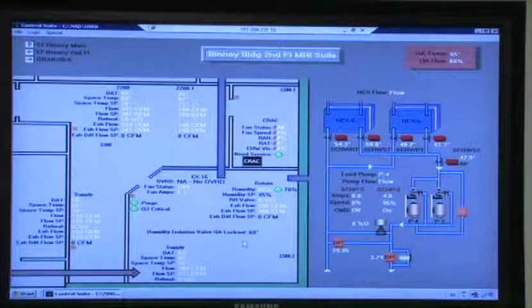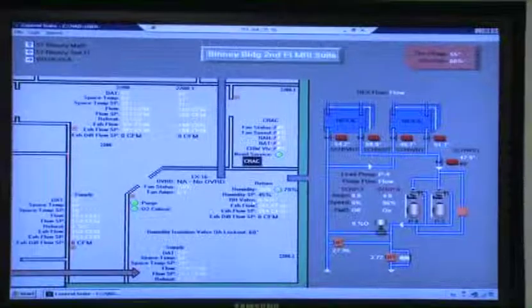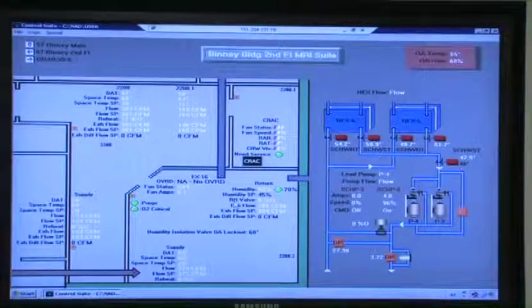When the outside air goes above 60 degrees, it closes this isolation valve and it isolates steam, it prevents steam going. Is it this thing here? Yes, that's on the return, so that would be your reheat valve. So they're going to shut off the valve? Hold on a minute. Shut off the steam.